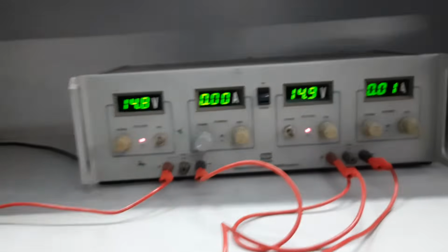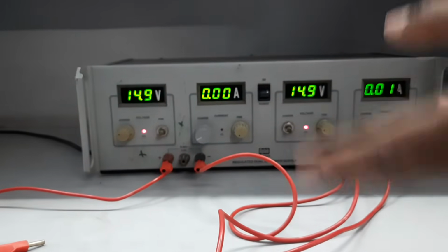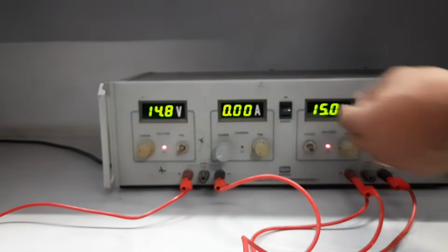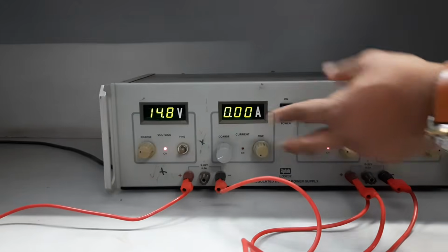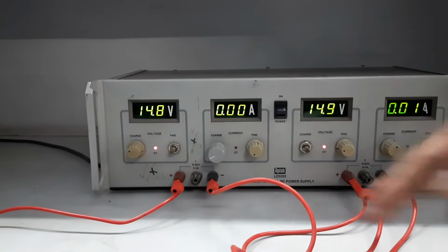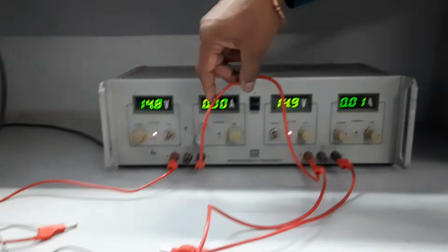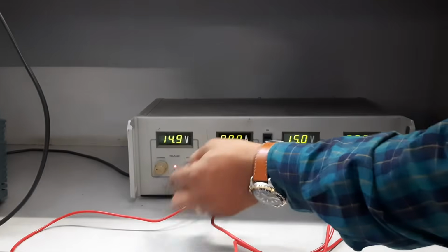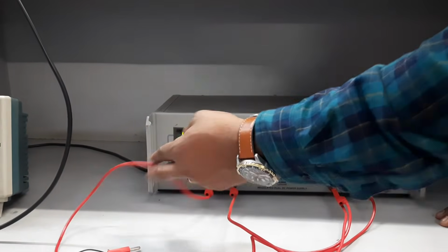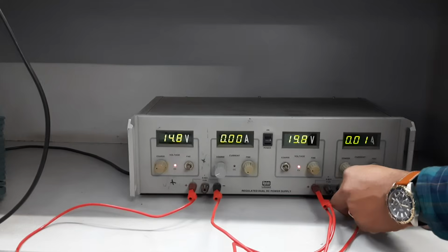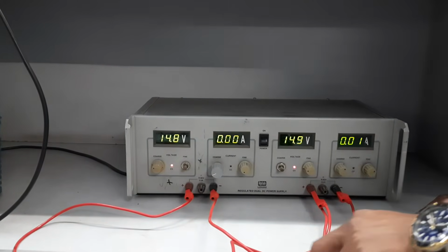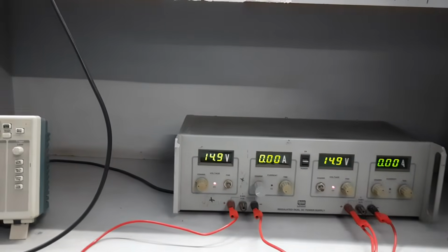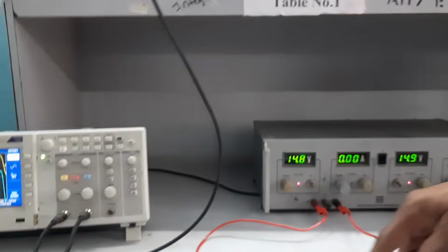Okay. So as I said, this op-amp requires plus minus 15 volt. With this knob I can arrange 14.9 at max, and it is fluctuating, so I can roughly say that it is 15 volt. Here 15 volt. So what I have to do is first short the plus terminal and minus terminal. From this I can get plus 15 volt, and from the minus terminal I can generate minus 15 volt, which can be given to the pins, that is, the inverting terminal and non-inverting terminal. This is how we can generate this. Okay, so same configuration.